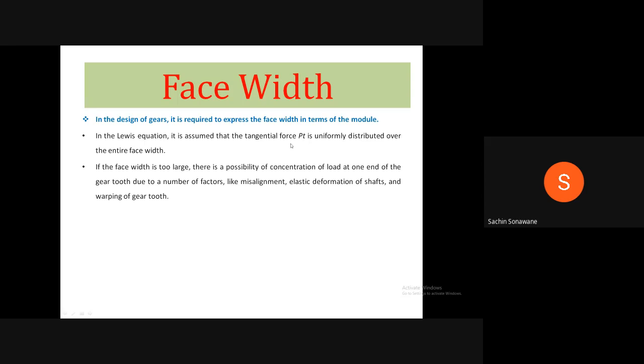In the Lewis equation, it is assumed that the tangential force Pt is uniformly distributed over the entire face width. If the face width is too large, there is a possibility of concentration of load at one end of the gear tooth due to a number of factors like misalignment, elastic deformation of shafts, and warping of gear tooth.